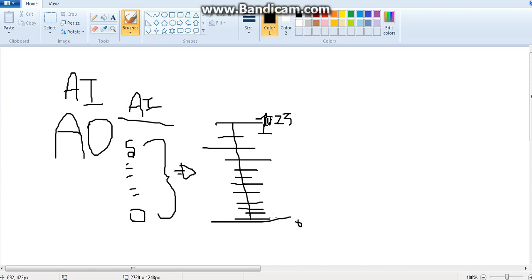So this is the first unit, right? If you count properly up to 1024 units, you will find the maximum value is 1023. Depending on the voltage coming, Arduino will fill up the units and give you a particular value. From that we can assume the voltage that is coming. Anyway, we are going to read the unit value. This is analog input.